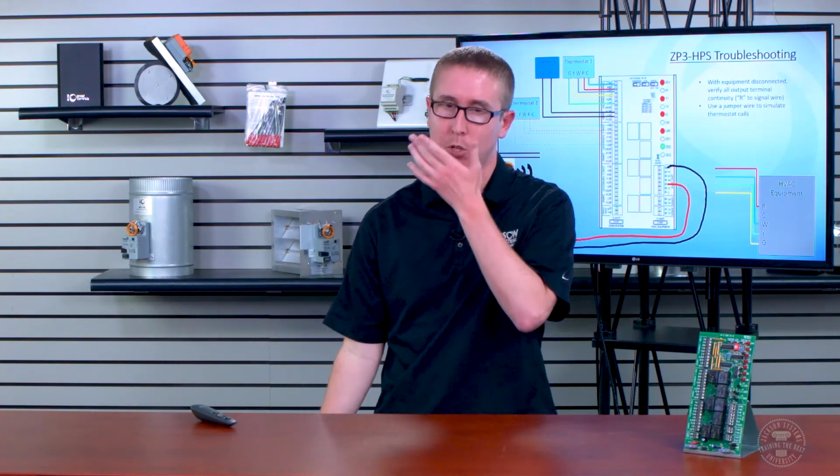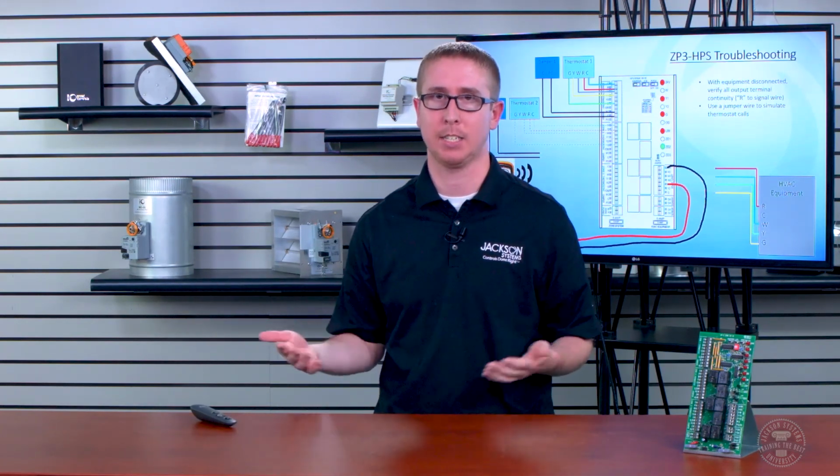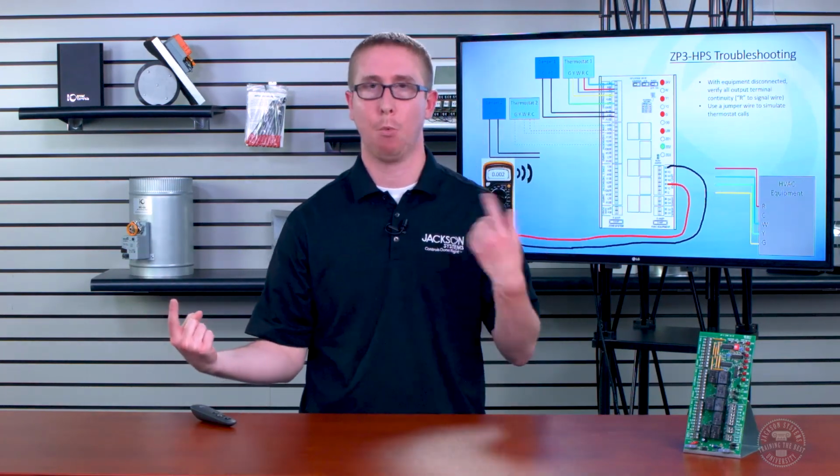So if you have a scenario, probably just call in and let us double verify. Basically, if you're looking to replace a damper actuator with something that's not the exact replacement, when you call in, know the size of the damper shaft, and we'll be able to get you the actuator you want with the shaft adapter if needed.